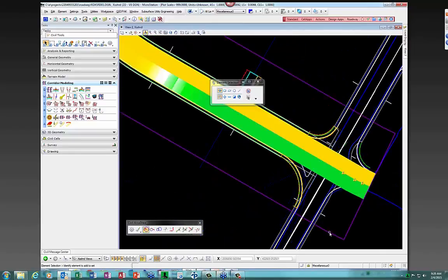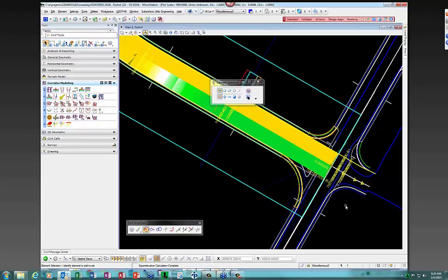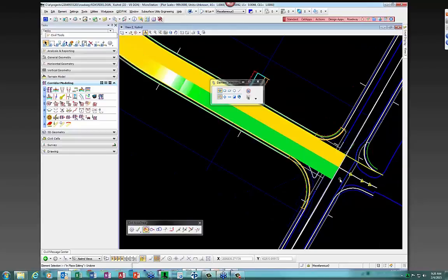But what I was going to show you is how if you wanted to change the limits of the whole section, you could just set it to a value of 700 here, and that would move the whole section and all the lanes with it. Or if you wanted to change something about a lane, you can click a lane, and let's say you had the wrong slope on it. Maybe it's supposed to be -3. You can set -3 right here, and it changes the whole section now. And notice the color is a little bit different. Then you can use the edit undo or Control Z, Control R in the superelevation edits.